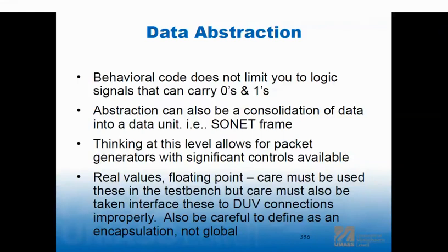Now I'm testing the order of the instructions, and I'm doing it randomly because if I had to write targeted test cases for every one of those, it would take forever and I would bias it all over the place. I randomly generate instruction codes and it processes those properly. I have a model of the processor that tells me for a given set of instructions what the results should be, and I compare the results. Maybe I just compare memory at the end.